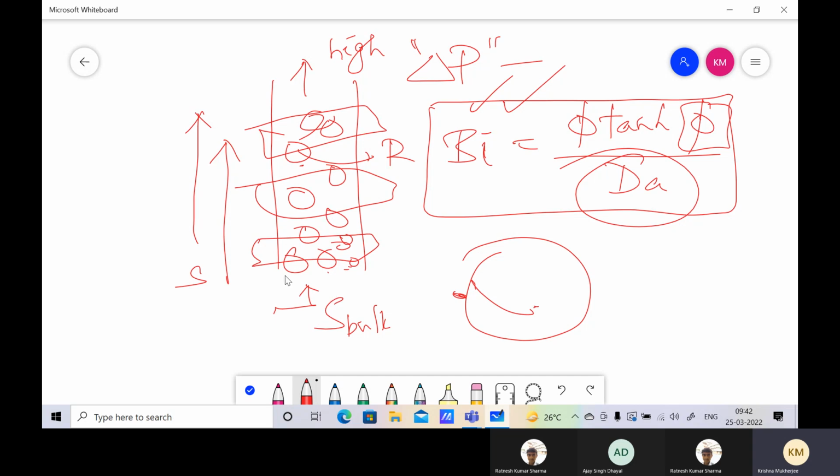And so this is a very interesting design problem of what kind of immobilized column you should make, what size of beads you should make, when you set up an enzyme reactor. And this is of course for the simplest case of V is equal to V max S upon Km plus S. These things become much more complicated, and I thought I would do all these things, but it's almost impossible. These are the kind of design problems that an IIT engineer is supposed to solve.